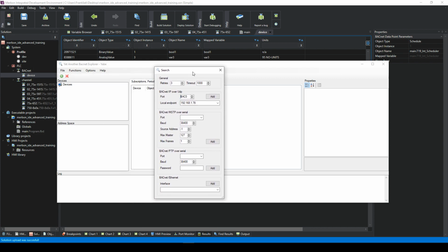If you are using clients, just make sure that they support the specific types of time programs or alarm points, because not all of the clients available on the market support all BACnet types of objects. They are all different. So just make sure that you are using a correct one.